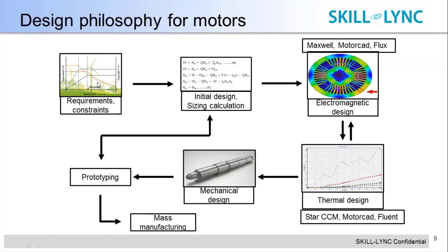If we talk about the design philosophy, first of all, as we discussed, motors are for multiple applications. So the very first requirement for motor designing is to understand your application very well. You have to understand the operating conditions and the torque-speed requirement. Is it a single speed operation or an application where the motor speed has to be varied? What are the efficiency levels required? Whatever information there is for the application, you have to gather it and understand it in great detail. Only then should you begin your motor design.